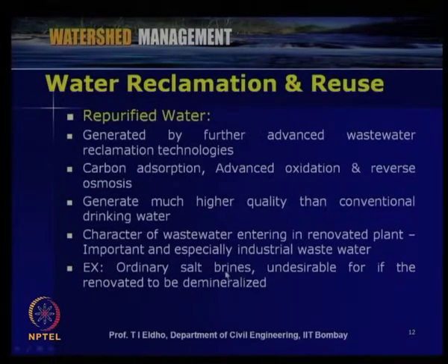For example, ordinary salt brines are undesirable if the renovated water is to be demineralized. If you are going to reclaim water from salt brines and have to remove all the salt content from the reclaimed water, then it will be much more expensive. So that way we have to see the cost of the reclaimed water.